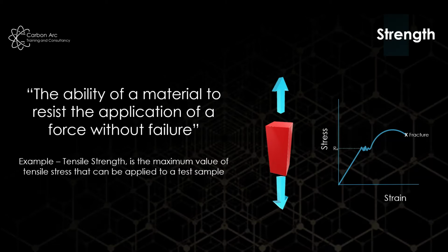In this graph, we can see we get a yield point, which is ReH. Rm is our ultimate tensile strength, or our UTS. We can work that out with the equations we've already talked about in one of our other videos, which I'll link above. You can see around the yield point, it jumps around. Here we have a yield higher and a yield lower limit, and that gives us the window in which yield is given. But we take an average of that, which is our Re.